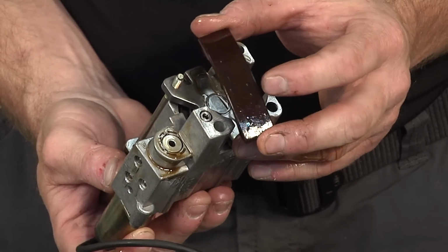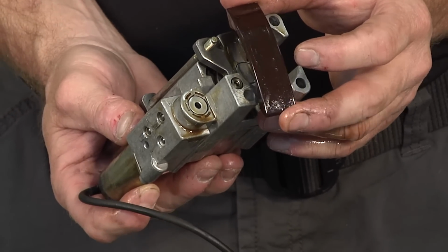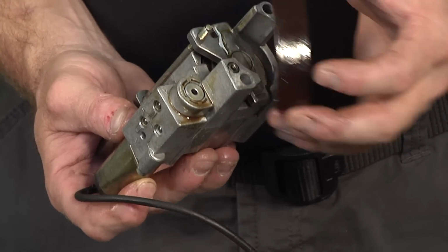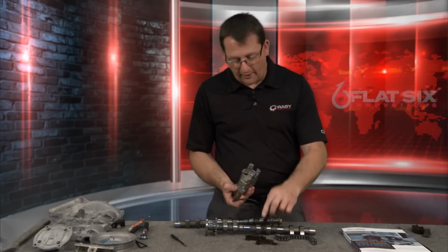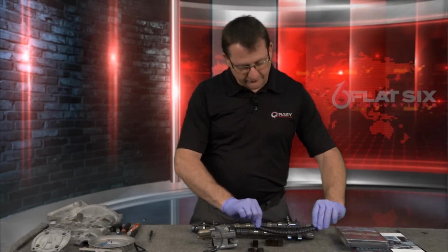So, you know, some of these are worn on the top side, some are worn on the bottom side, some are worn almost all the way through on both. I've seen these wear completely through, so there's no guide left. The guide is found in the oil completely in the sump, and it wears into the metal here. So after we've marked these discolored links, we're going to transfer those marks over to our replacement new chains.